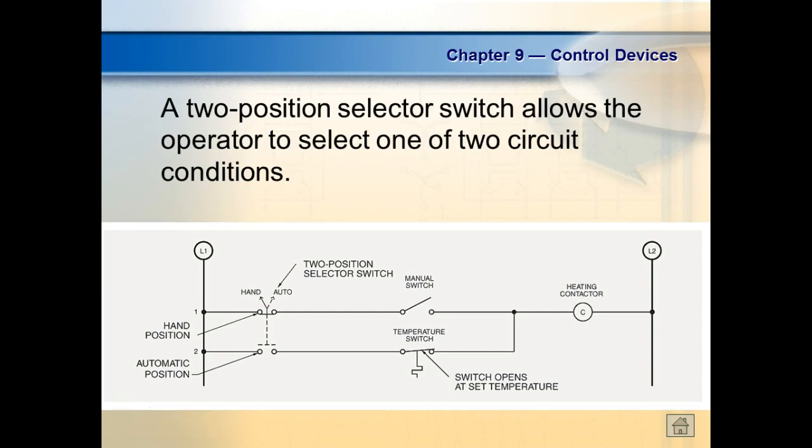So if you've got 8 switches in there, then you're going to have 16 wires coming. 8 on the input side and 8 on the output side, right? If you use all the switches. So yeah, this guy's going to have 4 wires coming because it's got 2 divisions, right? 2 on the input side and 2 on the output side, if you use all of it. I've never seen one. I'm not going to say that. We could only use one of the switches though, and call one of them off and call one of them on. And don't even wire the other 2 wires.